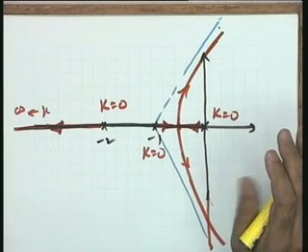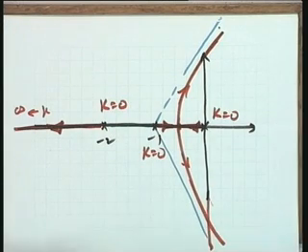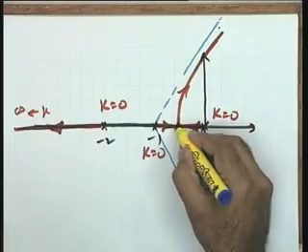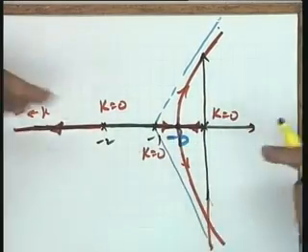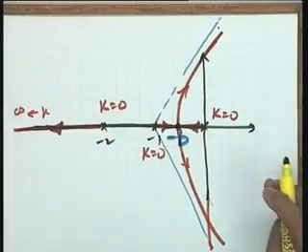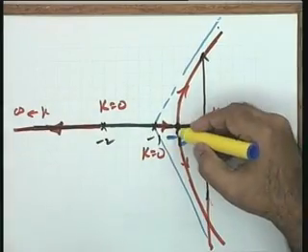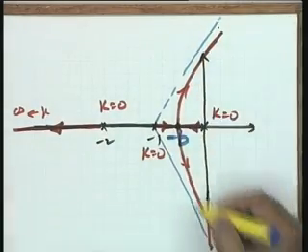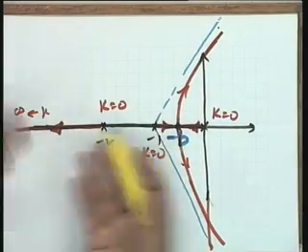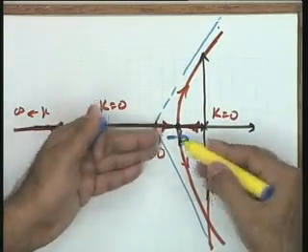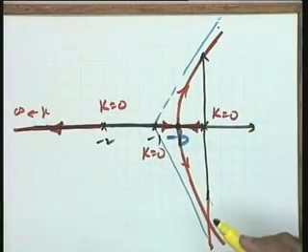So if I apply all these things on this particular case, probably this could be the root locus diagram available with me. Now you see that one point, if I had this particular point, let me call this point minus B, the point at which the 2 root locus branches break away, I would have been in a more comfortable situation to make a root locus sketch. There cannot be a breakaway point here because the root cannot break away. Here only the 2 branches are meeting and they will break away.